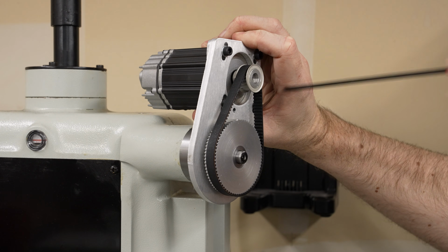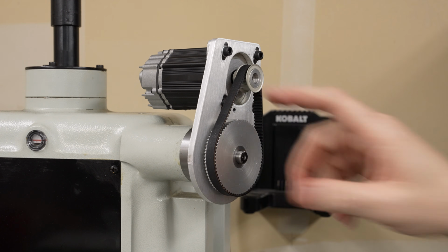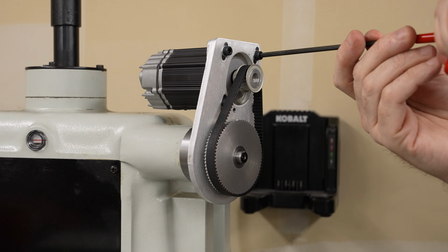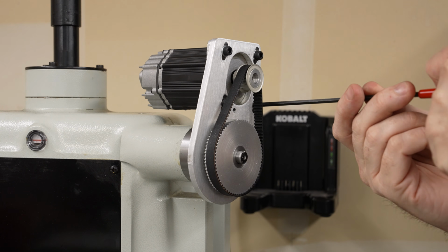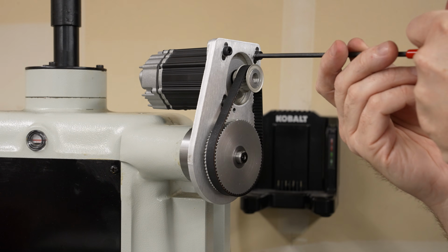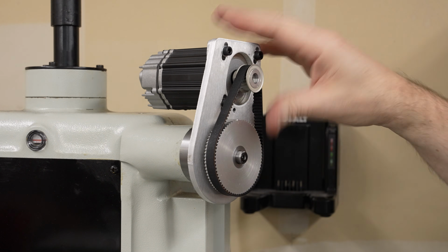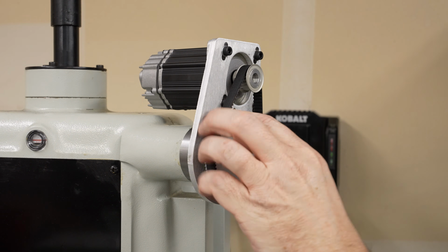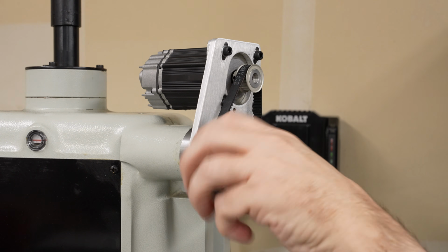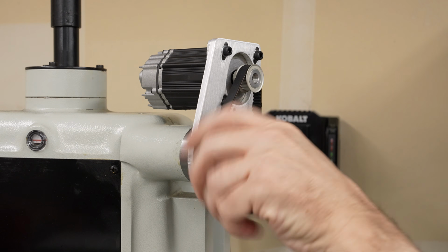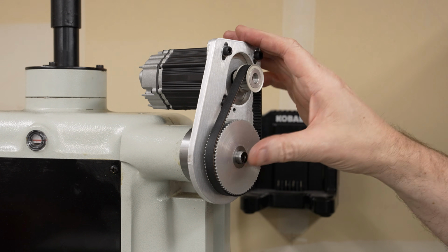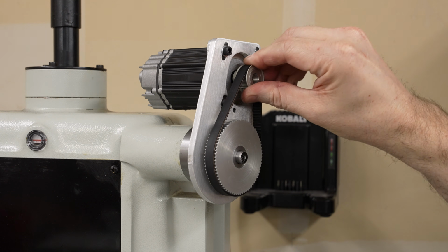Put some pressure on this with my thumb and tighten it down and just see how we're doing. And that tension seems pretty good, so I'll just lock it in place. It's easy to come back and adjust it later. Put enough torque on these that they won't slip, they won't move. And that actually looks pretty good. I expected to have to fiddle with this for a little bit, but no, I think that tension's going to be fine. There's not a huge amount of torque right here because of the multiplication of force from the lead screw. So I think this is okay. If it's not, I can always come back and adjust it later.